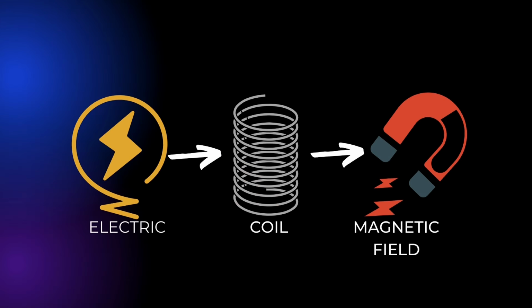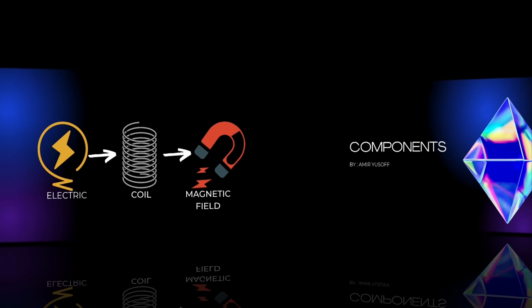For the concept, a power supply in the top of the metal detector activates the transmitter circuit that passes electricity down through a cable in the handle to the transmitter coil at the bottom. When electricity flows through the transmitter coil, it creates a magnetic field all around it.